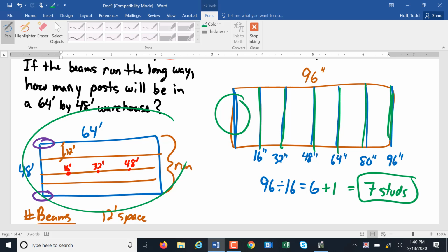I did a lot of concrete for years, and rebar is a tough one to figure because you've got the bends and the bending loss and overlaps. I worked on the county watershed projects, so you have to factor all the engineering into that. You have to have 18-inch overlap between rebars, and at least 3 ties per overlap.